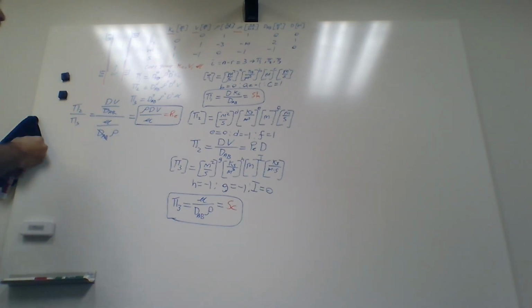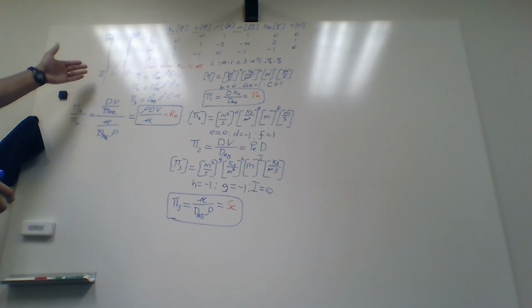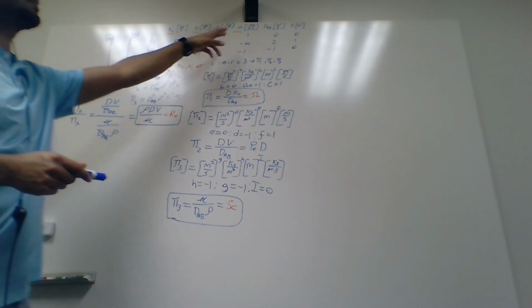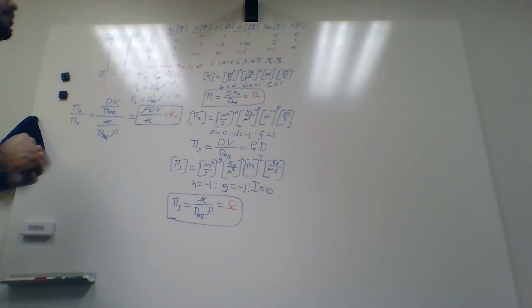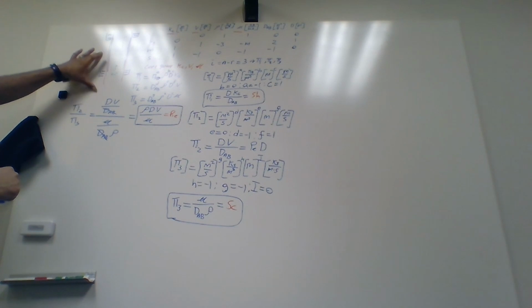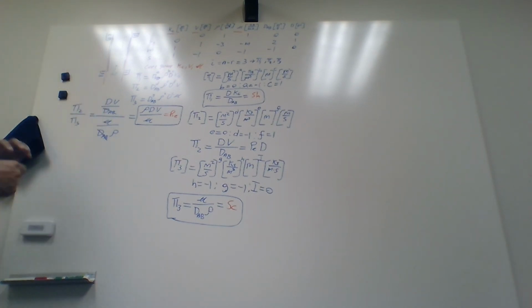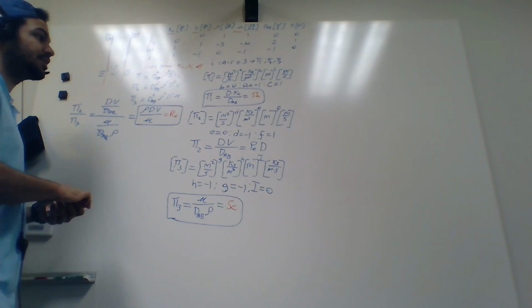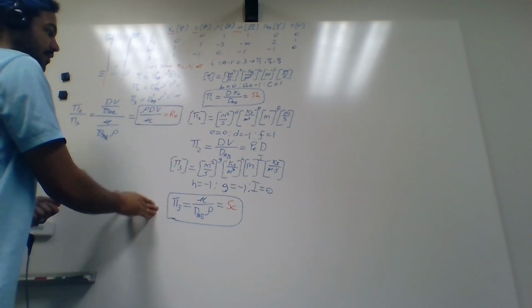Now, looking at our scenario of having a wetted wall pipe with air blowing across it, we determine that these 6 variables relate to the mass transfer within this system. And then we did dimensional analysis to determine the Sherwood, Schmidt, and Reynolds number.